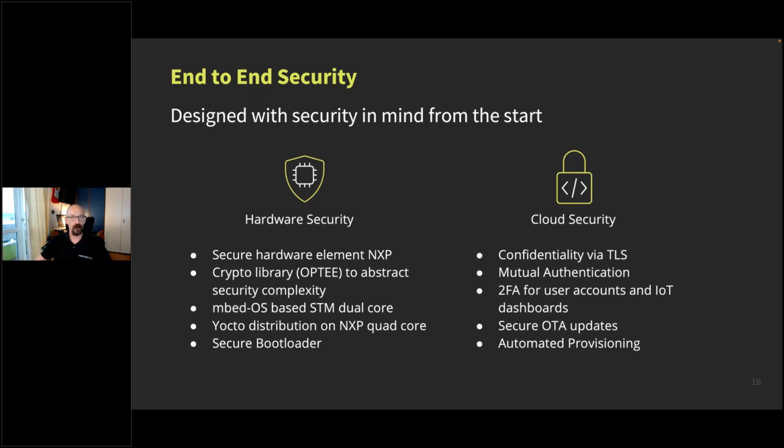As I said, from the hardware standpoint, we have the secure element, but we have also provided a crypto library. In this case, for the X8, we are using OP-TEE, a small operating system that is born for interacting only with secure elements in order to abstract the security complexity.